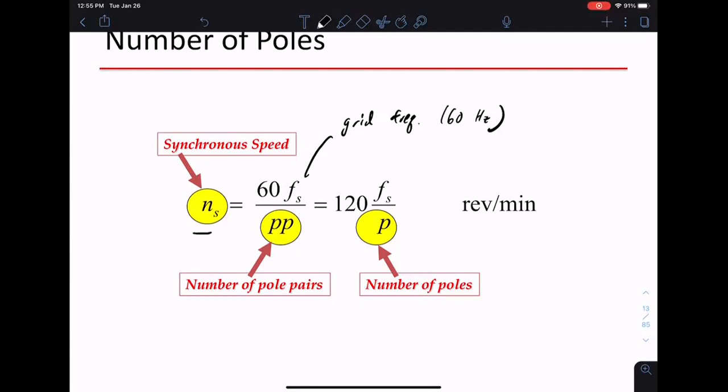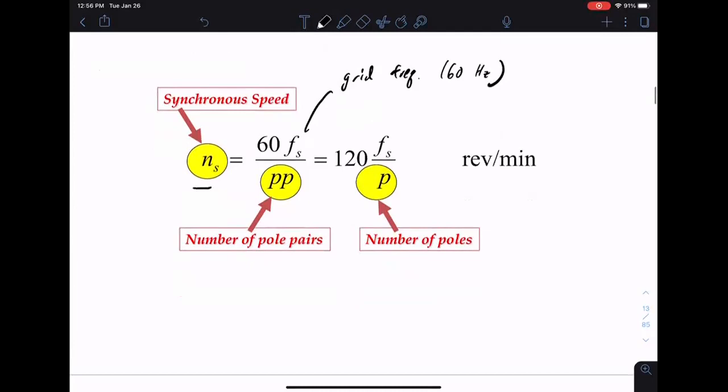And the way we slow it down is also such that we cannot slow it down to any arbitrary speed. So remember the possible speeds. We have 3600 RPM. This is certainly possible. This is a single pole pair machine.